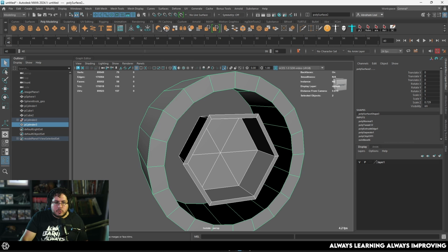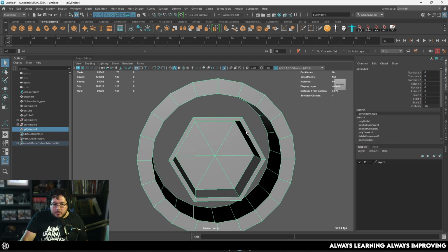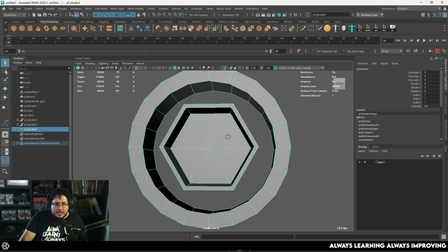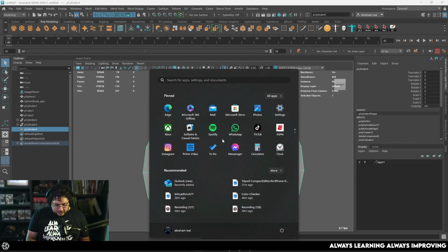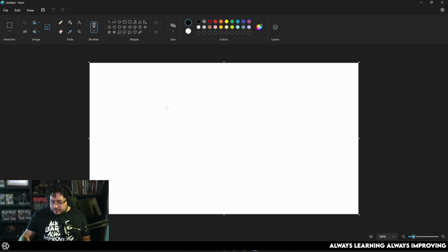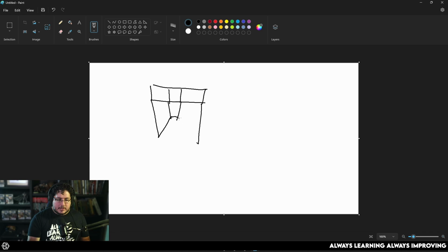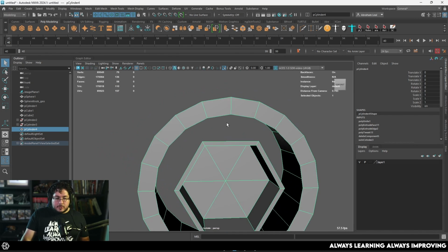Now, these two guys, of course, we're going to combine into a single object. We combine it so that we can work together with the topology side of things. And the interesting thing about this is that we need to do a very common topology trick that's called simplification, but in this case it's reverse. Usually, when we have 3 edge loops like this, what we do is create a little trapezoid shape. We push this like this, and we minimize from 3 elements to 1. Which allows us to create this sort of subdivision. In this particular case, we're actually going to do the opposite. We're going to start with 1, and we're going to go into 3, so that we get a little bit closer to the final result.